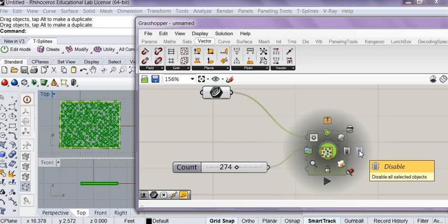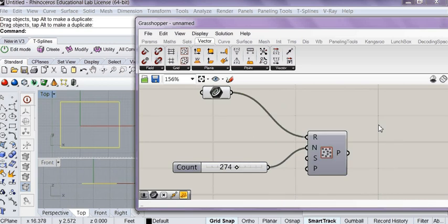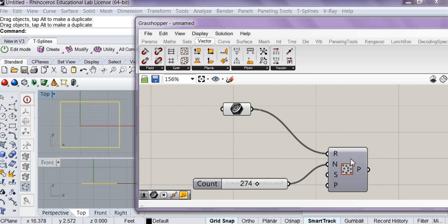Disable is very simple. Like in AutoCAD, you can freeze a layer, right? So basically, it will eliminate that operation from the memory. So here the same. You can disable that. It doesn't calculate. If you only hide, that component still in the calculation, right? So that's the difference. So right now, let's maybe just hide it. So you see this turns to gray color.